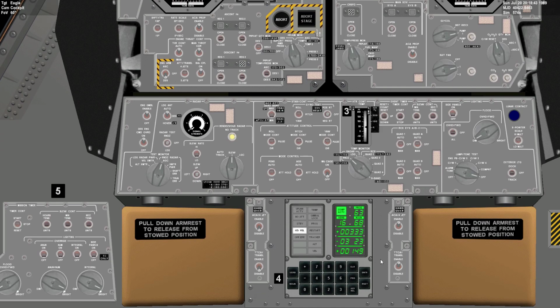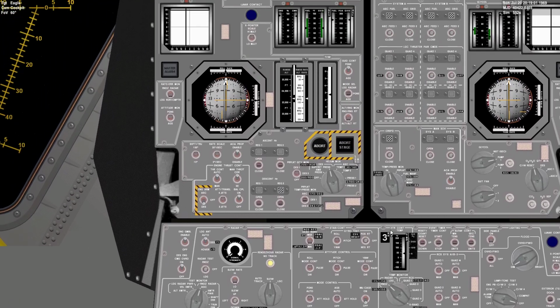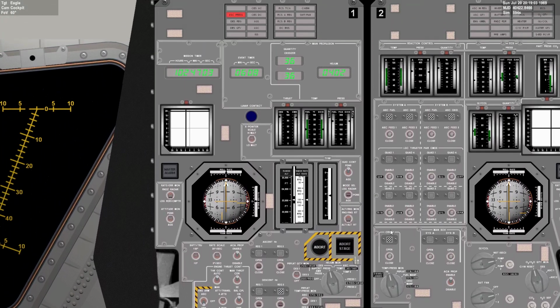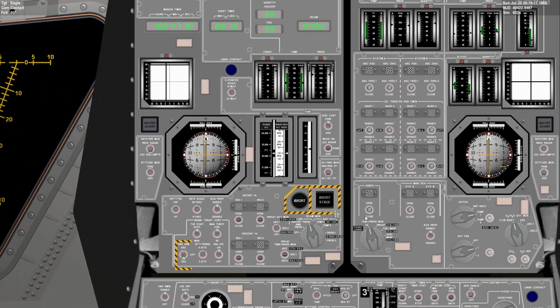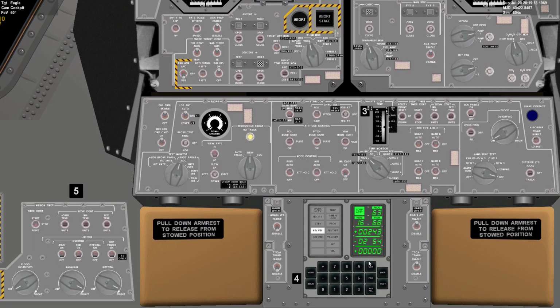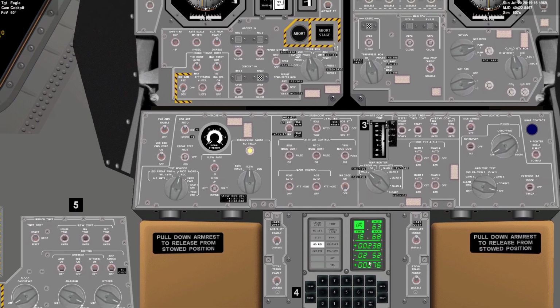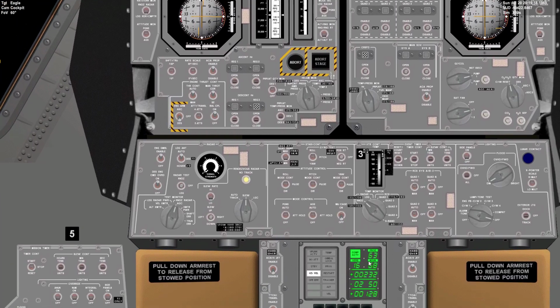This also puts the AGC into a lower power state, so it doesn't heat up quite as much while we're doing the demonstrations. It lets us not be exercising the current switch module when we can't watch it with the full monitor alarm panel. And we can do all the other demonstrations with internal erasable when we have the monitor up before we get into NASSP here. But unless I can root cause the problems in the next few days, we'll probably just be flying like this with simulated erasable.